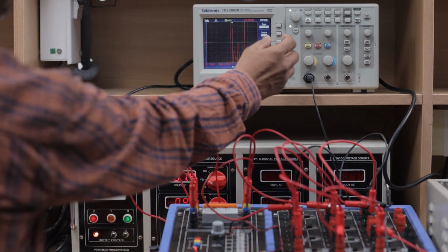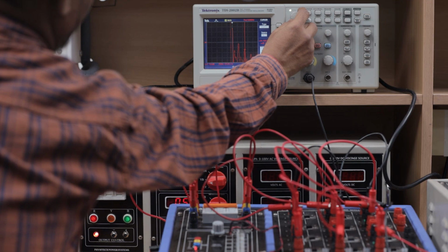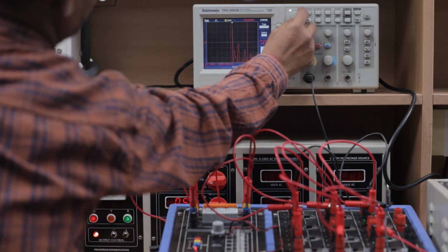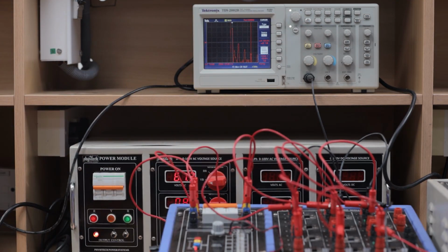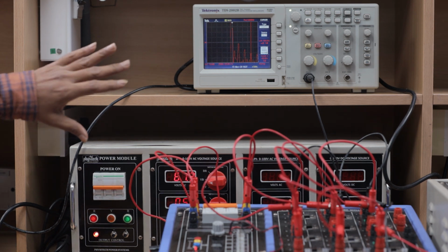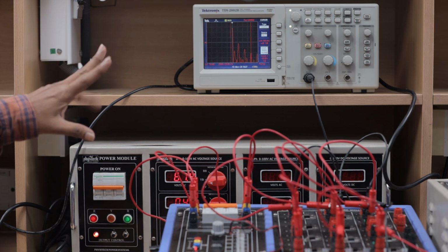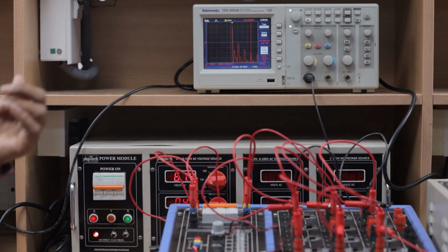Now we'll move the cursor to 900 Hz as the third harmonic. At 900 Hz, the dB value is minus 9.79 dB. This value you can convert into V fundamental RMS. Actually, we are observing three different frequencies, but capturing only one fundamental frequency is sufficient to attach in the result file.